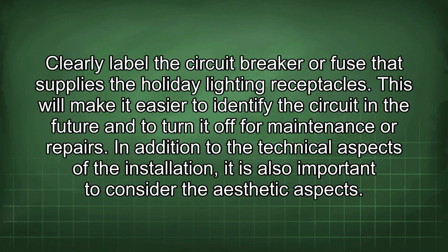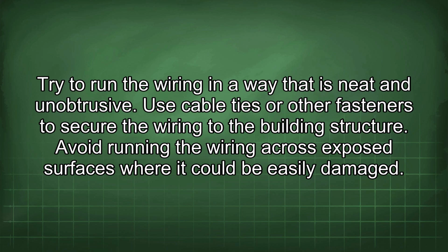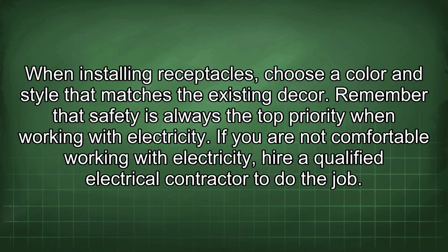In addition to the technical aspects of the installation, it is also important to consider the aesthetic aspects. Try to run the wiring in a way that is neat and unobtrusive. Use cable ties or other fasteners to secure the wiring to the building structure. Avoid running the wiring across exposed surfaces where it could be easily damaged. When installing receptacles, choose a color and style that matches the existing decor.